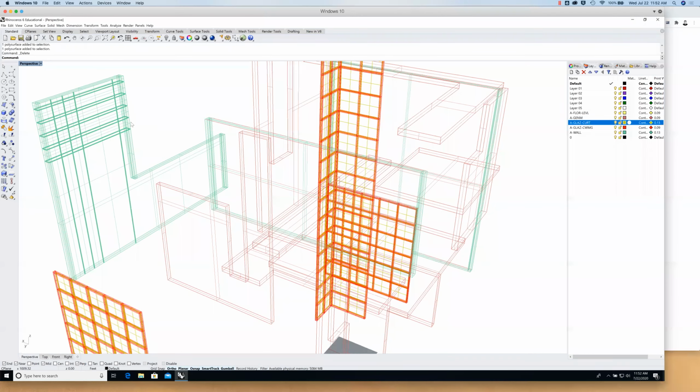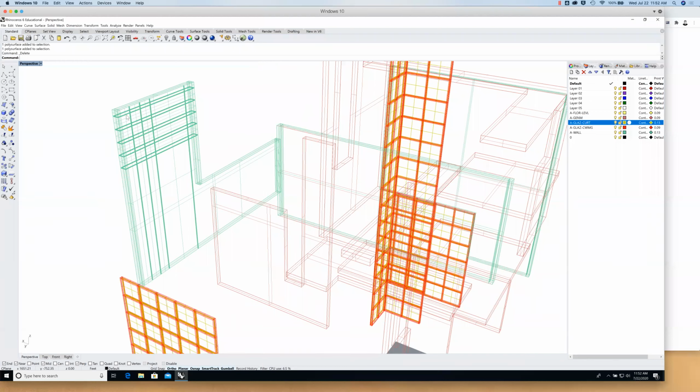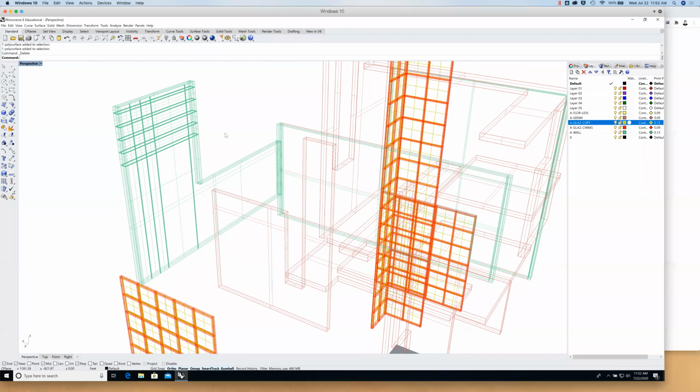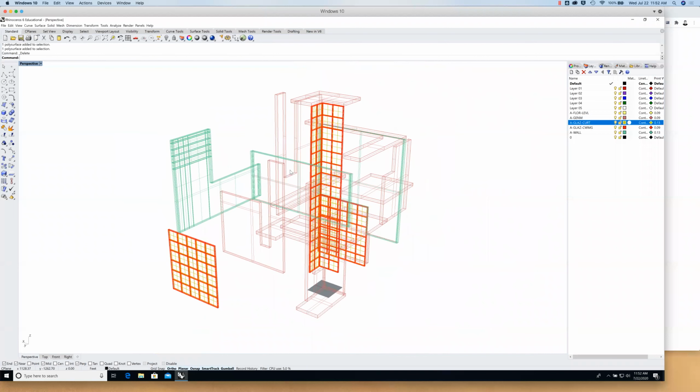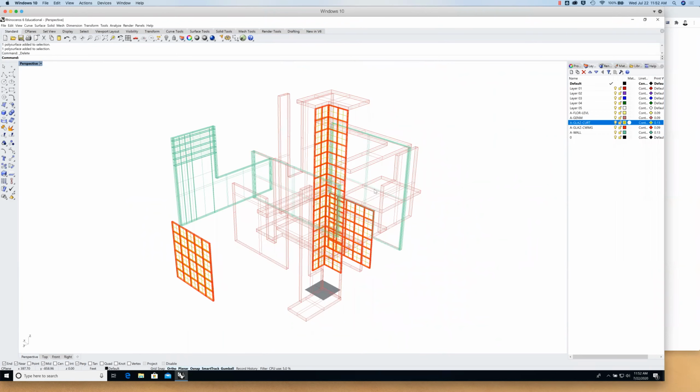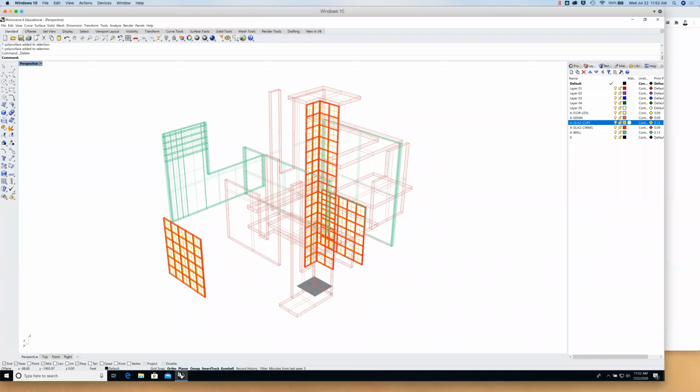And so you'll need to do that. For the extrusions that we actually put reveals in, you'll need to go back through and delete the original extrusions. Otherwise, you won't see the reveals because when we look at this, they'll be hidden inside of the actual original extrusions, right? So, okay.